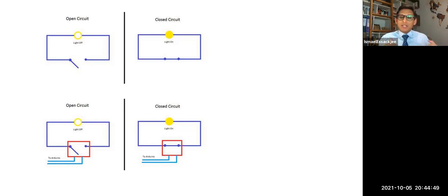So what is a relay? It is just a device which is going to help. The Arduino circuit is going to give the command open or close, and this relay is going to switch on or off another circuit. At times we have normally open or normally closed depending on the relays, and it can switch it on or it can switch it off depending on the command it is getting.